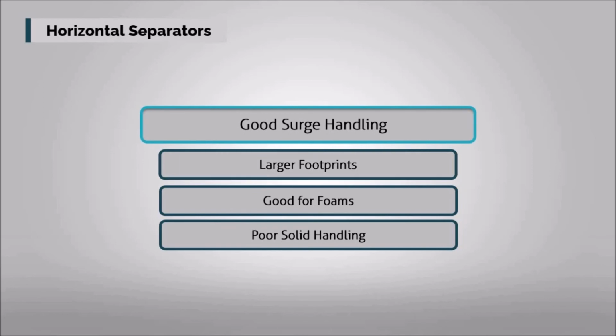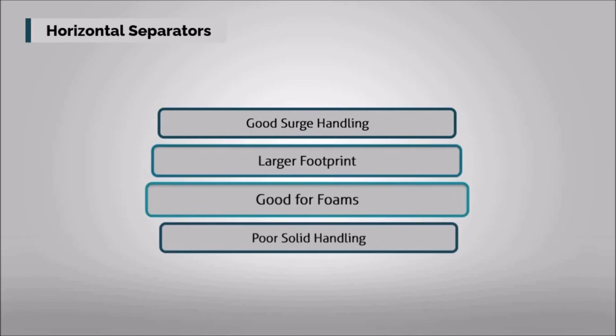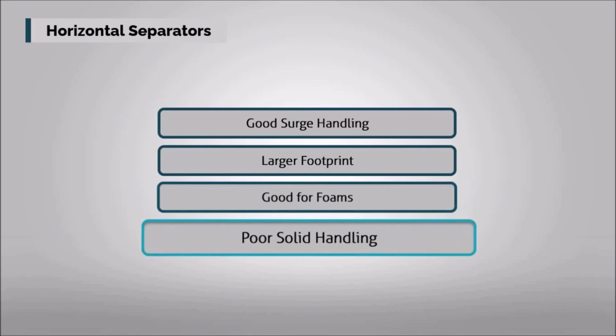And later, the access systems are important, as with the vertical separators. Because of their height, vertical separators are harder to access, while horizontal separators make the relief and control systems easier to access. The horizontal separators are better at dealing with foams that are caused by either bubbles produced by the inlet deflector or by liberation from the bulk oil phase, which can reduce the separator's handling capacity.